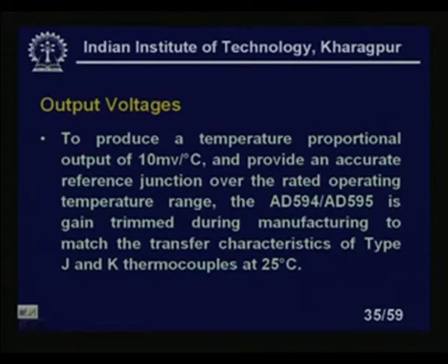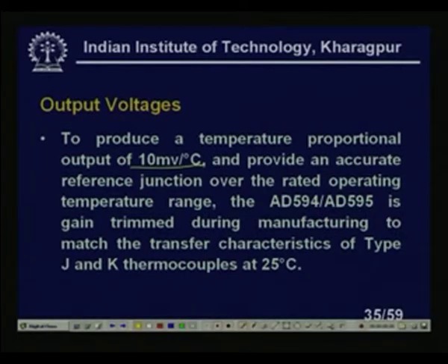platinum-rhodium platinum thermocouple, it is 10 to 12 microvolt per degree centigrade, which is quite low. But here you see at the output I am getting 10 millivolt per degree centigrade. So sensitivity is extremely high. You can see here this sensitivity is quite high. So it is already signal processed and we are getting so much sensitivity here. So the resolution obviously will increase.